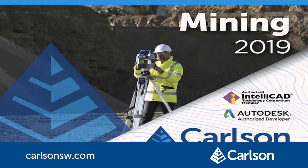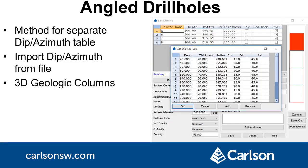Now let's look at Carlson Mining. Support for angled drill holes has been expanded. You can now have a table of dip and azimuth values by depth that is independent of the strata list. The dip and azimuth data can be imported from a separate input file. Draw 3D geologic columns has new options for labeling along the angled drill holes.